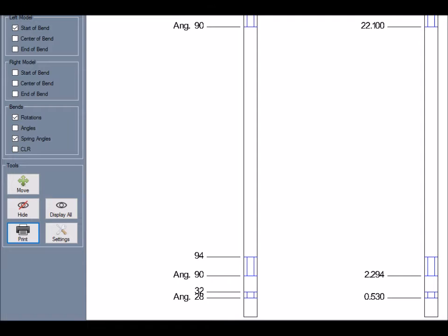And then the other thing it does is it is specially calibrated to allow us to compensate for what's called spring back. Anytime you bend a piece of metal, when you stop bending it, it kind of springs back just a little bit. So our dies are specially calibrated prior to doing any of this for our specific tubing bender and for a specific type of tubing as well as a specific wall thickness. And what that lets us do is it lets us know exactly how much they're going to spring back on any given bend. And the software has all that built into it based on calibrations that we've done.